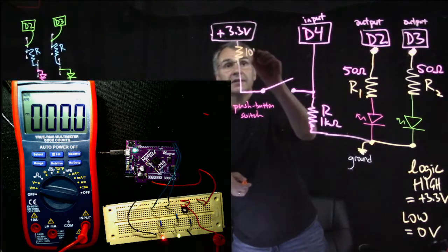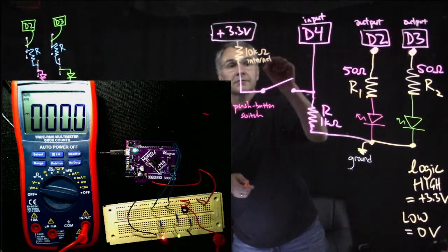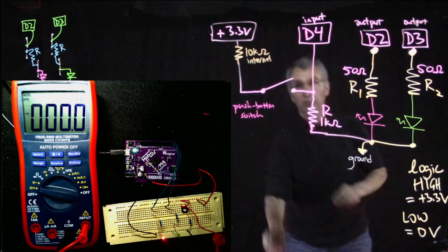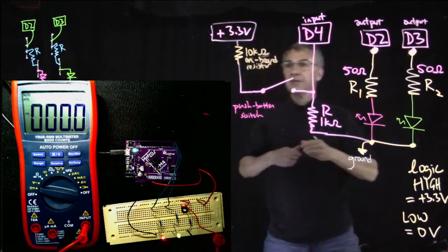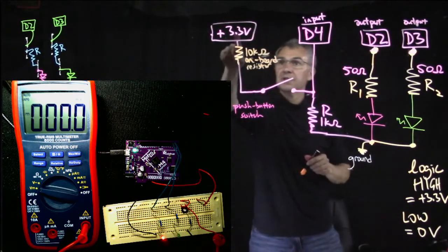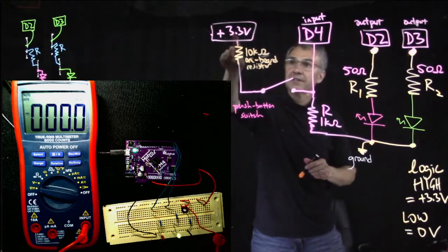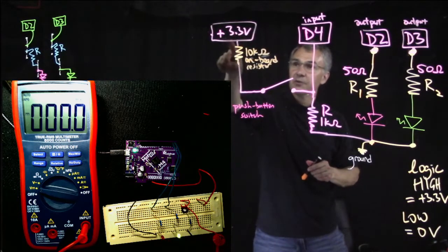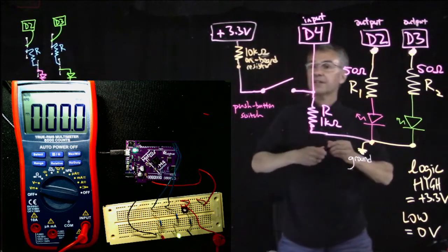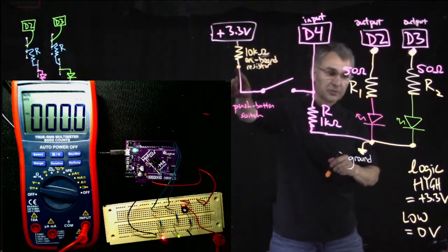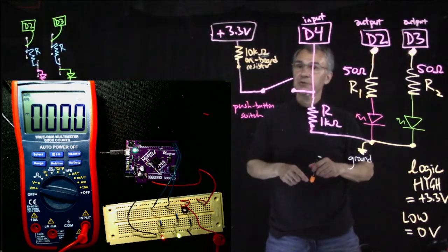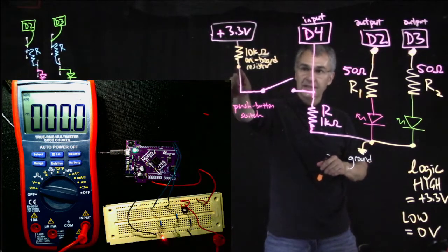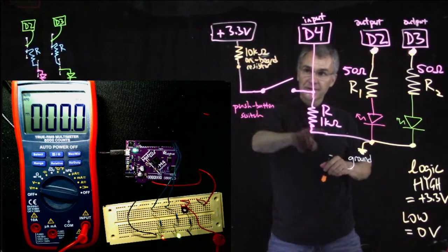putting a 10 kilo ohm on-board resistor. So I think when I plug into the 3.3 volt, I'm not really plugging directly into 3.3 volts. I'm plugging into this end of a 10K resistor, 10 kilo ohm resistor, the other end of which is actually wired to 3.3 volts.